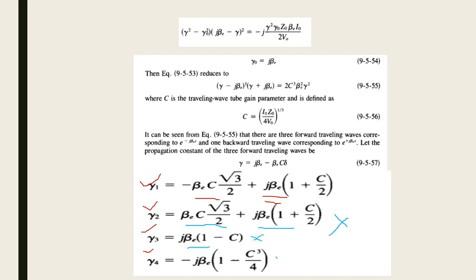What is interesting is this mode. In this mode, can you check that it is minus j beta e. So minus j beta e means the wave is propagating in the backward direction. Please note, backward direction. What do you call that? Suppose from the source to destination, something is coming back from destination to source. We call it feedback. And feedback always results in oscillations. Hence, this gamma 4 mode, please note students, very important, this gamma 4 mode always works as BWO.